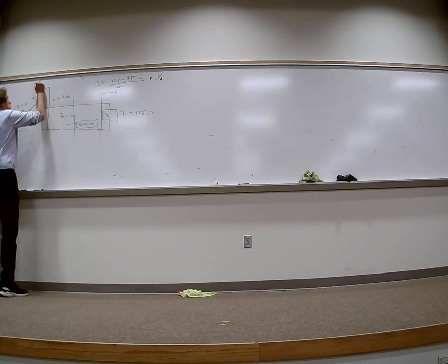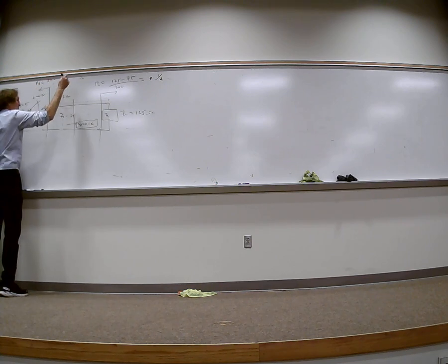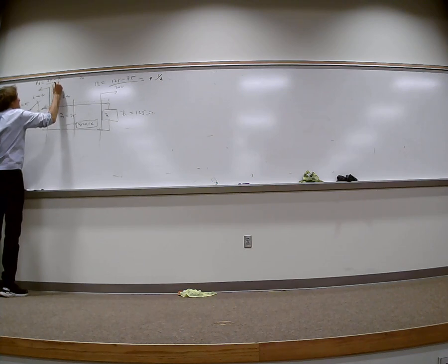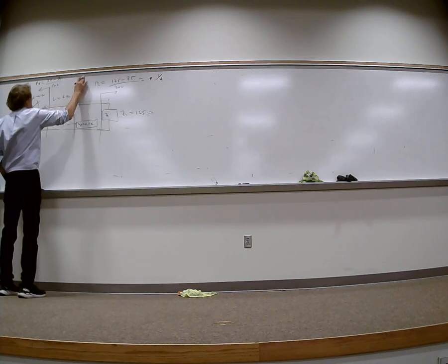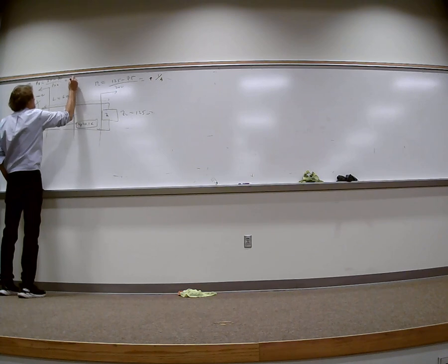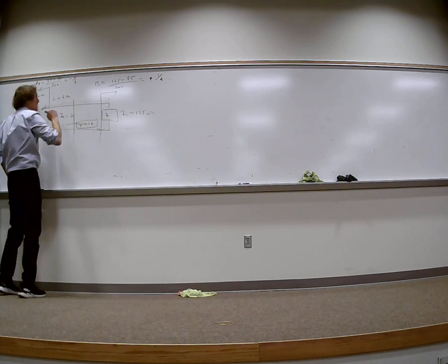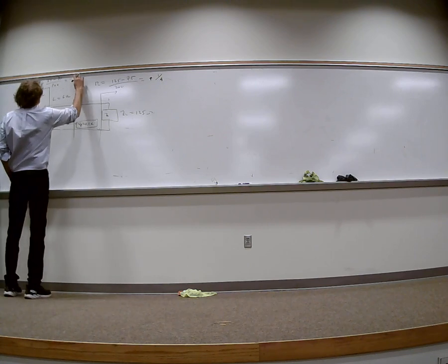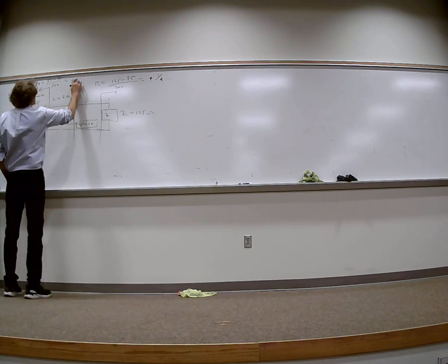Next I'm going to get the reflection coefficient of the source. That's going to be 25 minus 75 over 25 plus 75, or 100. And that's going to be minus 3/4, right? You all agree with that? Sorry, minus 1/2. My bad. Minus 1/2.